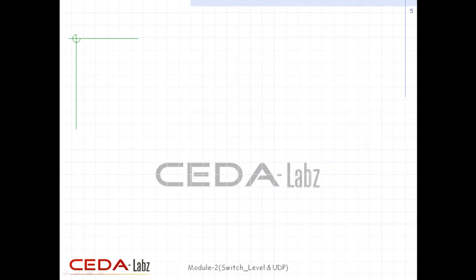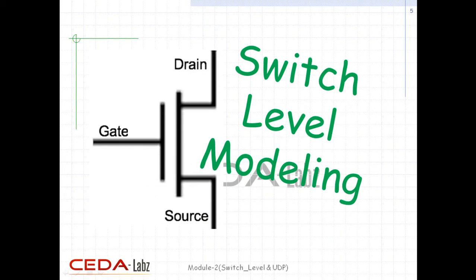primitives. Earlier we learned digital design and simulation at a higher level of abstraction such as gates, data flow, and behavior. However, in rare cases designers will choose to design the leaf-level modules using transistors. Verilog provides the ability to design at a MOS transistor level. Design at this level is becoming rare with the increasing complexity of circuits and the availability of sophisticated CAD tools. Verilog HDL currently provides only digital design capability with logic values 0, 1, X, Z, and the drive strengths associated with them. There is no analog capability.